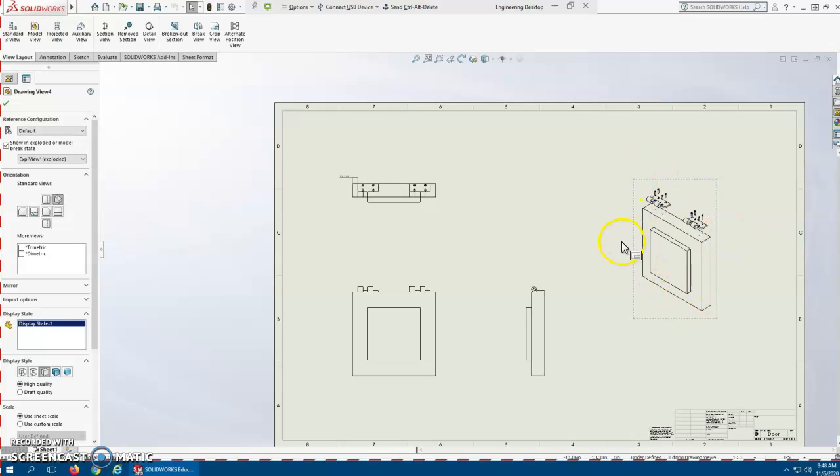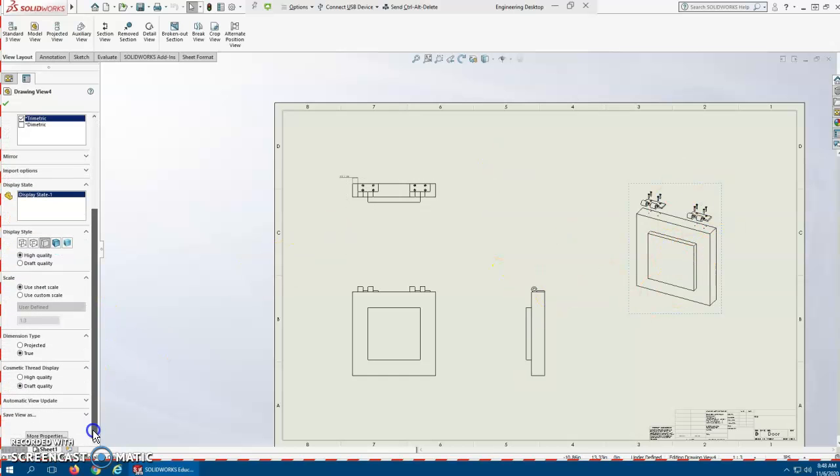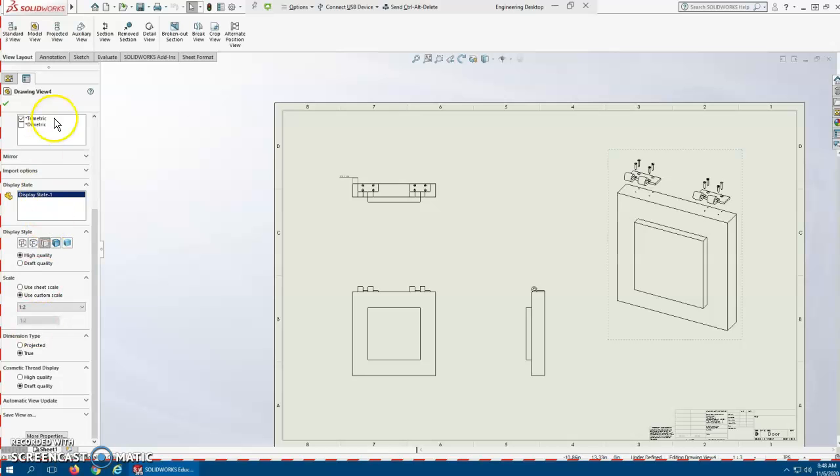Now the one thing I've got going on with this is, because of the isometric view, which is typically what you use, we don't have it really spaced enough for that. So let's take a look at, okay, we'll use the trimetric view, which just rotates it a little bit more. And actually that is, if you're following along in the textbook, what the textbook uses. And actually this guy is a little bit small for what I want. So let's go and make this one a 1:2. Kind of fill the whole thing in.